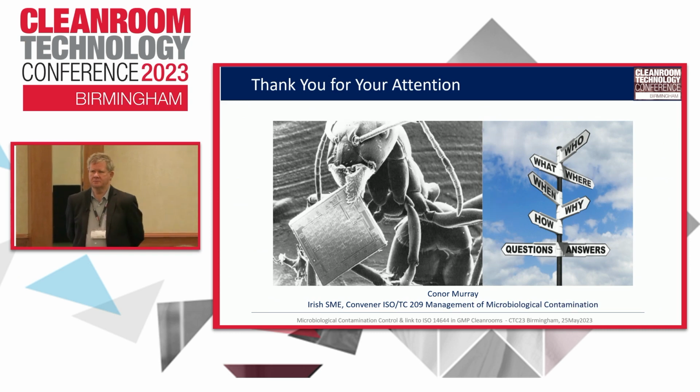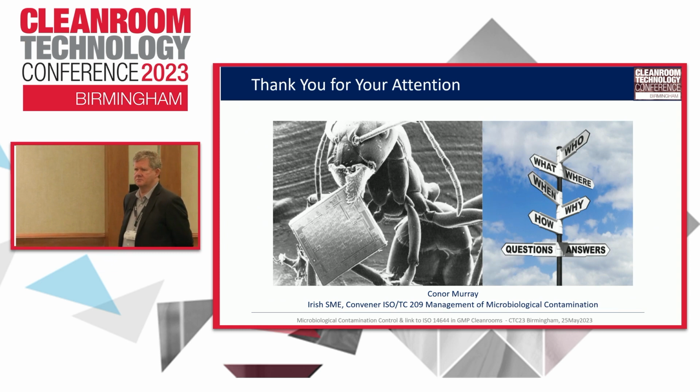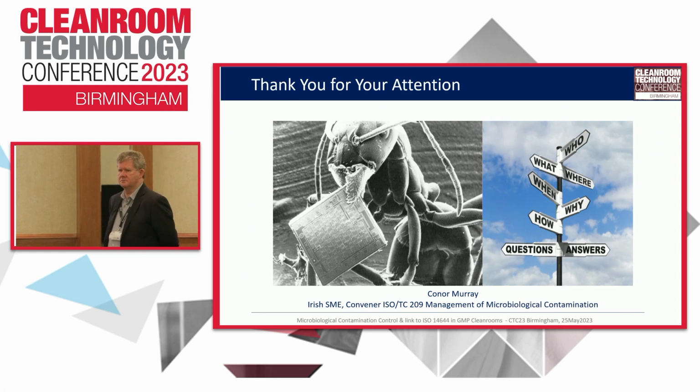Not more of a question, but more of an observation. I've been in the contamination control monitoring industry for nearly 30 years. One of the biggest problems I see is the misconception between certification and monitoring, and the application of the certification tables to the monitoring process. And with the monitoring environment, it's really all about trending.